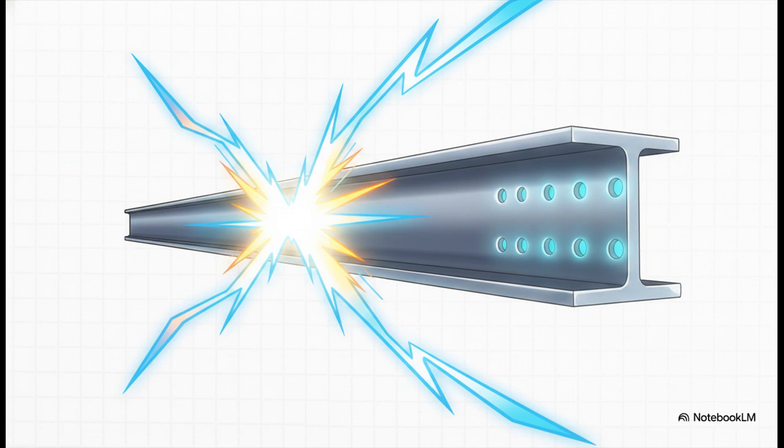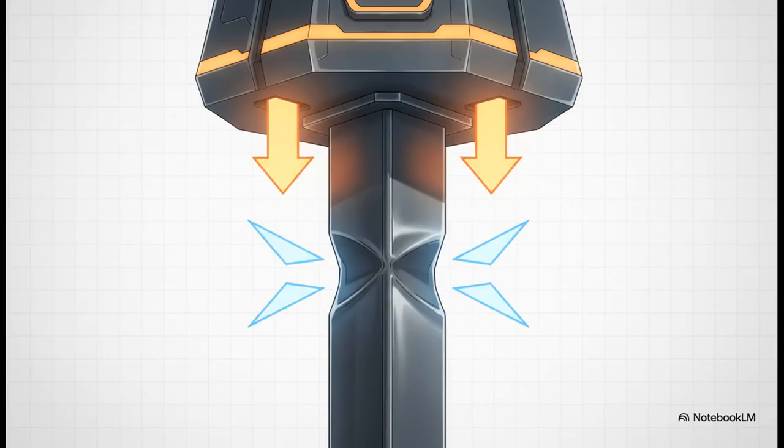The rules in this chapter dictate exactly how much pulling force a steel shape can take before it yields or fractures. The code calculates the gross area of the steel and, critically, the effective net area, which accounts for any holes drilled into the steel for bolts, because, as you know, those naturally weaken it. That's instantly followed by compression in Chapter E.